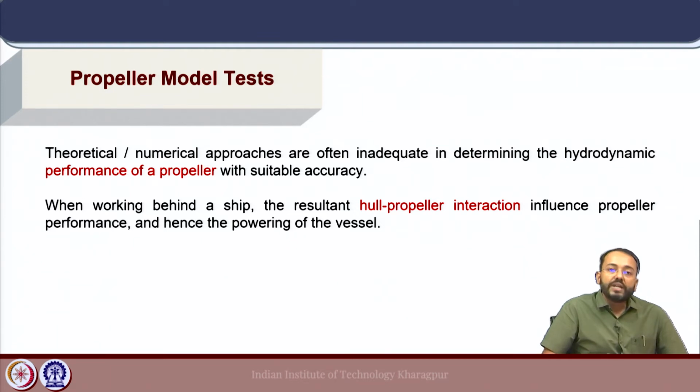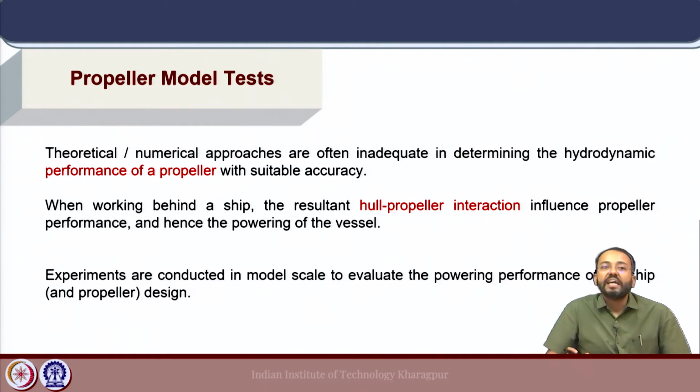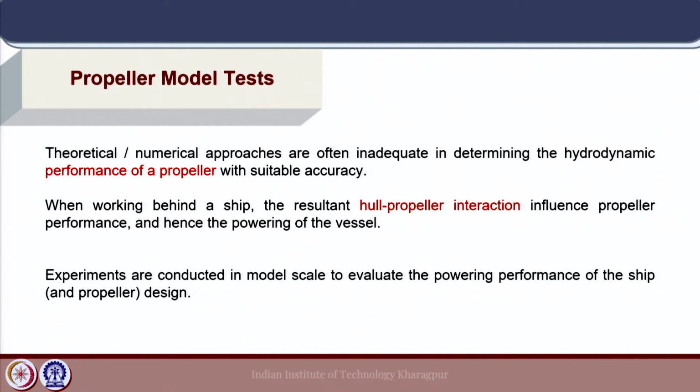So, we have propeller model tests both in open water condition and the self propulsion test to evaluate the performance of propellers, and these experiments are conducted in the model scale, and we use suitable extrapolation methods to evaluate the performance of the propeller and also the ship and propeller together to assess the powering performance of the ship.